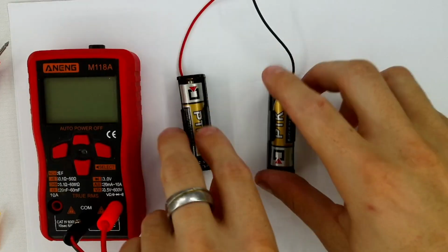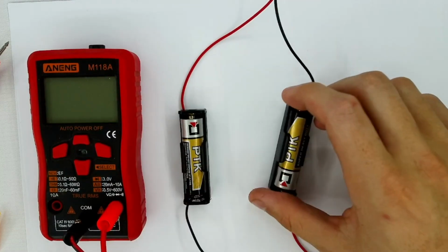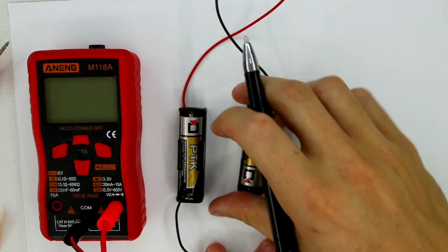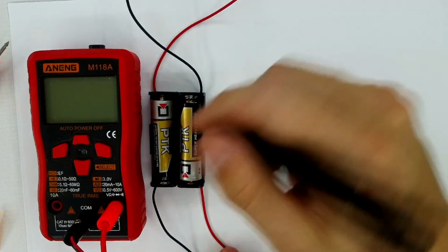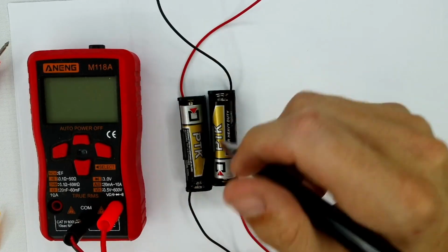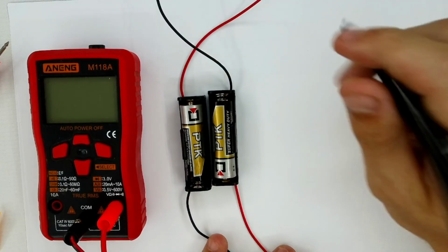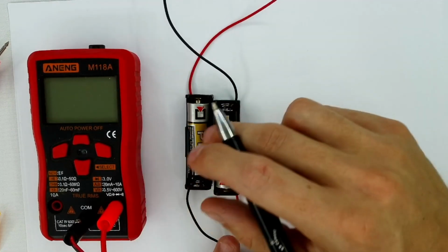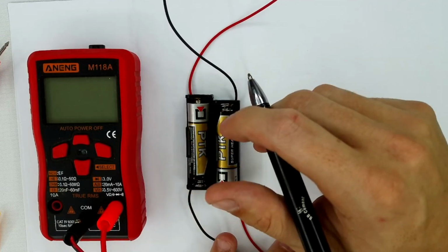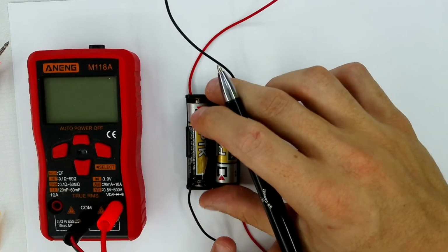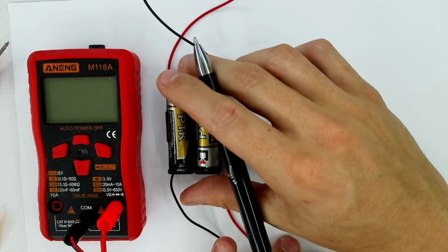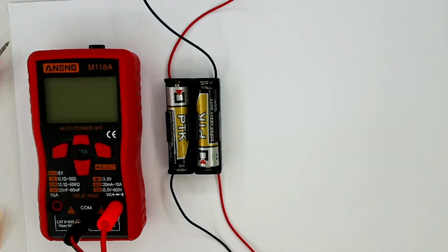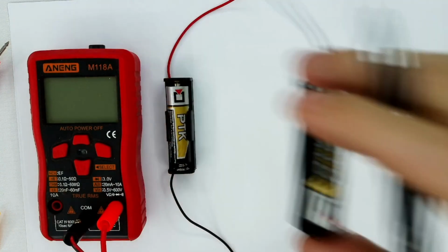Okay, so we're going to be using these two batteries, which we are going to be connecting in parallel. Now let's have a look at a parallel circuit. What are the main characteristics when we connect these batteries in parallel? When we connected them in series, we noticed that the voltage got increased. So we added the voltages together and therefore got our total voltage. But with parallel connections, our voltage actually remains the same. There is no new positive or negative point. We actually create a common positive and negative point between these two batteries, basically shorting them out to each other.